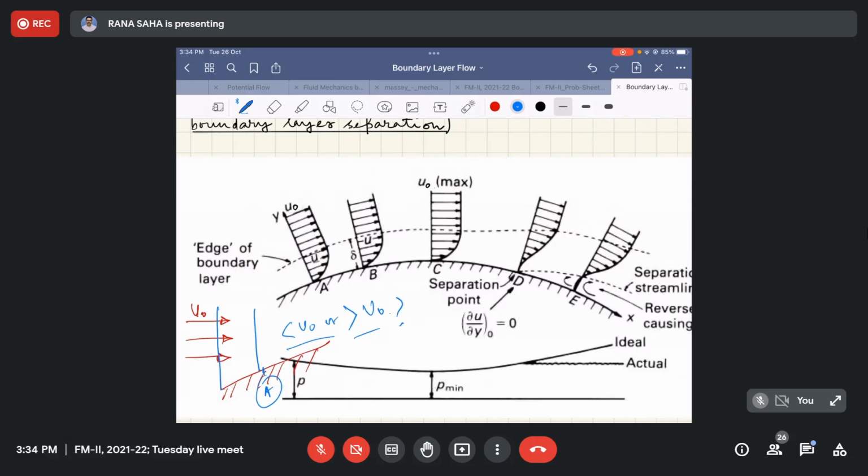And then we are actually here. I am just showing you another analogy that is beyond the boundary layer. What is being shown here, edge of boundary layer. Beyond that, the situation will happen like that. Okay, and beyond that boundary layer, if the velocity gets decreased or increased, eventually here it is being increased, as we have correctly said. So if it is being increased now, from your Bernoulli's equation we can prove that pressure will get decreased, isn't it, at this cross section A?